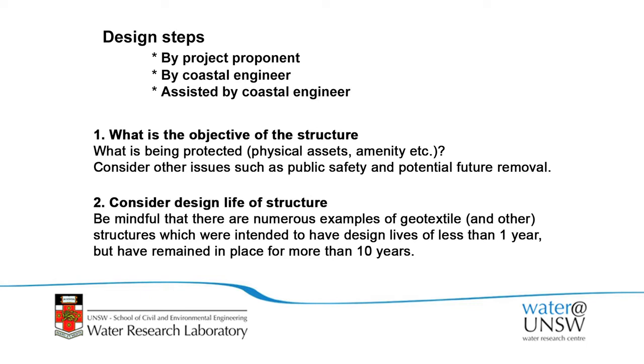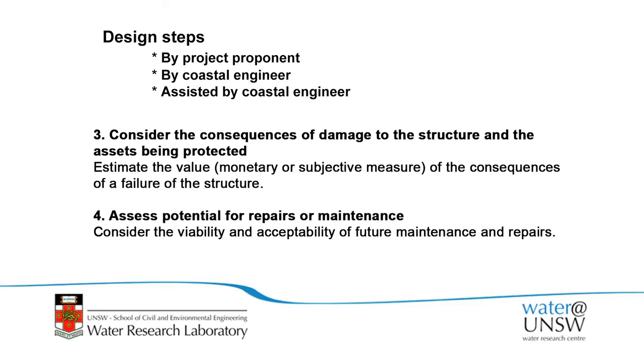down the track. Second step is to consider the design life of the structure, being very wary of the example I showed of Stockton, where often that's far exceeded, but nevertheless, at least consider what the design life you intend to have for the structure is, and realise that may well be extended far beyond what you originally intended. Also consider or document the consequences of damage to the structure or the assets that are being protected.